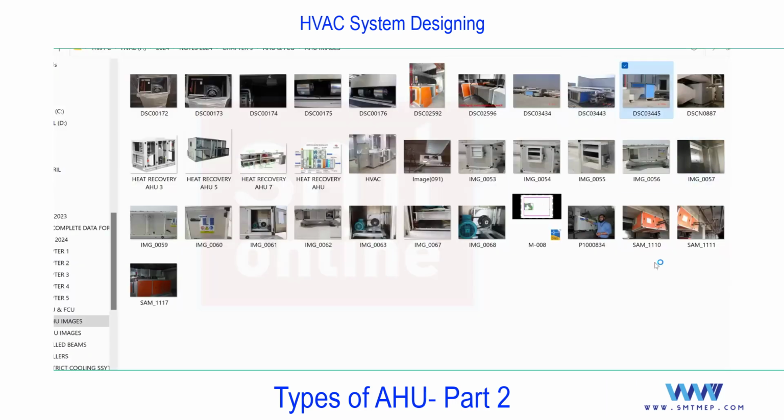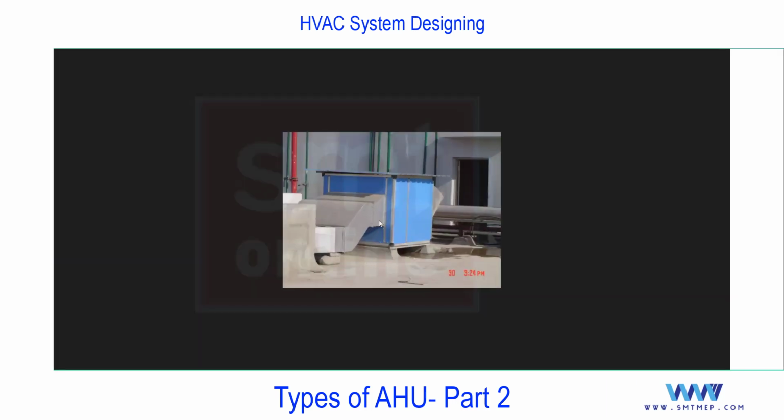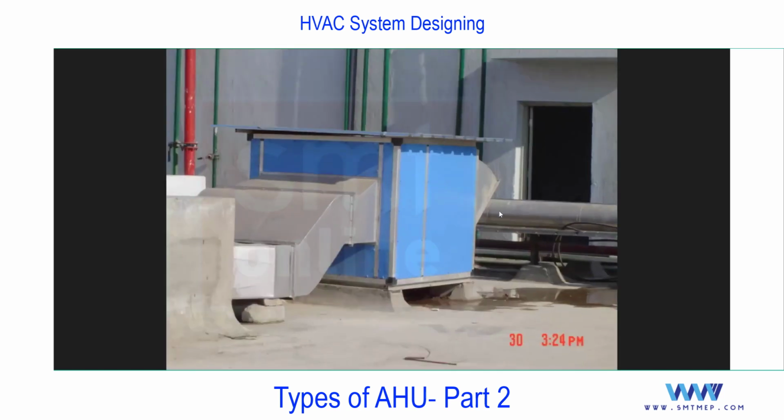Or else you can find this image. In this you can find the supply duct, and at the back side there is only a coil piece. There is no return duct. So this unit is used to suck complete fresh air as per the building requirement, and it does not mean that this duct will supply to one space. This duct is used to supply the fresh air requirement for multiple spaces.